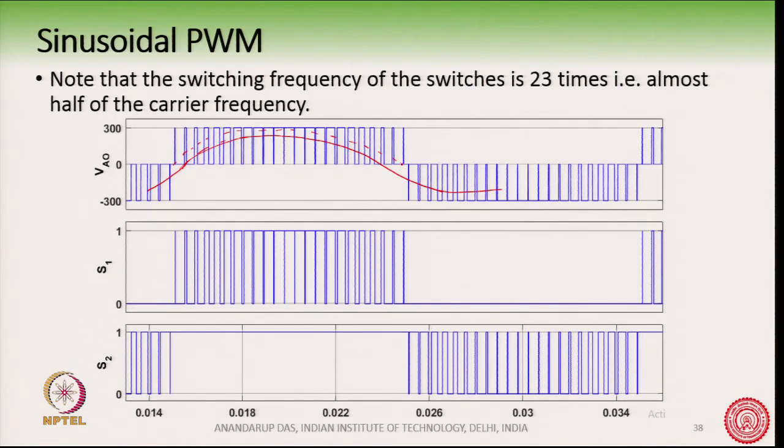For this condition, you can see that S1 has both switching and conduction taking place during this time, whereas S2 has only conduction losses, as it is fully turned on. So, this is going to create more losses in S1 as compared to S2.